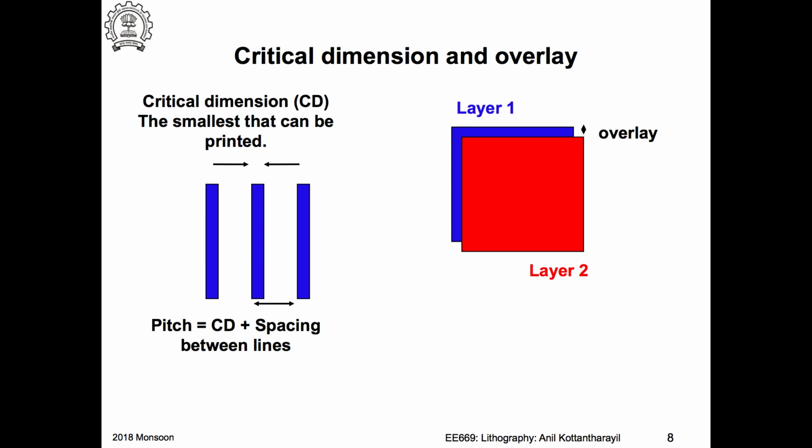Okay. So the feature size, there are many tricks to play to actually get your feature size very small. So you can see people actually printing 20 nanometer lines using a 193 nanometer wavelength lithography. Final feature on the wafer is 20 nanometers. That's possible. But I can't reduce the pitch very aggressively.